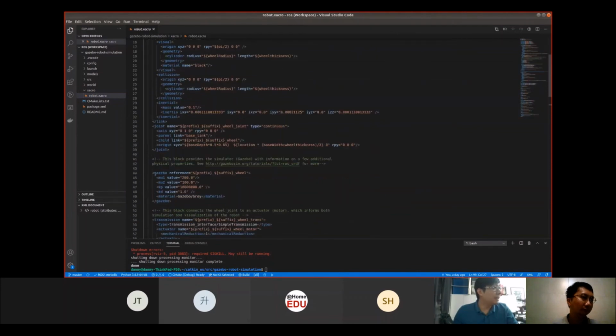There is the surface friction. There's a mu1, mu2 for the contact surface, if you can see on my screen, and there's also KP. This is deformation. Like when you touch the thing, how much it will bounce back and things like that. So if you put in the correct material property, you should be able to get back the correct response from the simulation.